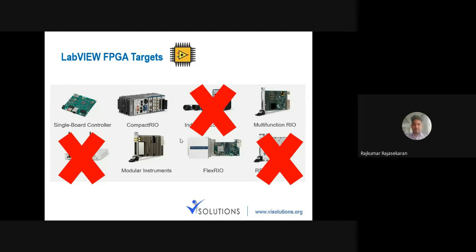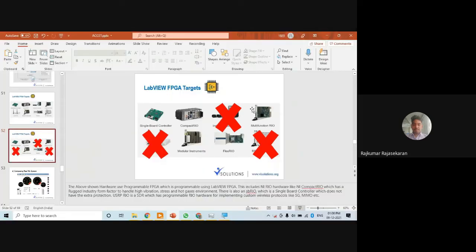In most of the systems here, both RT and FPGA will be in the same hardware itself. RIO hardware comes with both processor and FPGA in the same form factor. A single board also comes in the same form factor, and all of this will be connected to something called PXI. NI PXI makes use of a CompactPCI port behind an instrument computer. In short, PXI is an instrument computer which comes with multiple PCI buses, in order to make data transfer much faster.